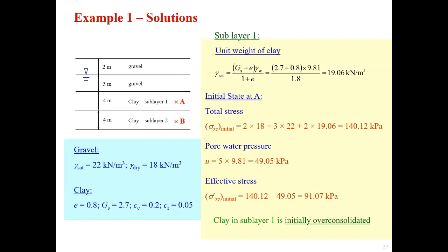So now, because we are trying to use the formulas we learned in this lecture, obviously what we need to do is work out the initial sigma O prime, sigma P prime and sigma F prime, then find the relative position, and then plug into the 3 sets of formulas to calculate the settlements. So that's our target. But before that, we need to collect all the given information.